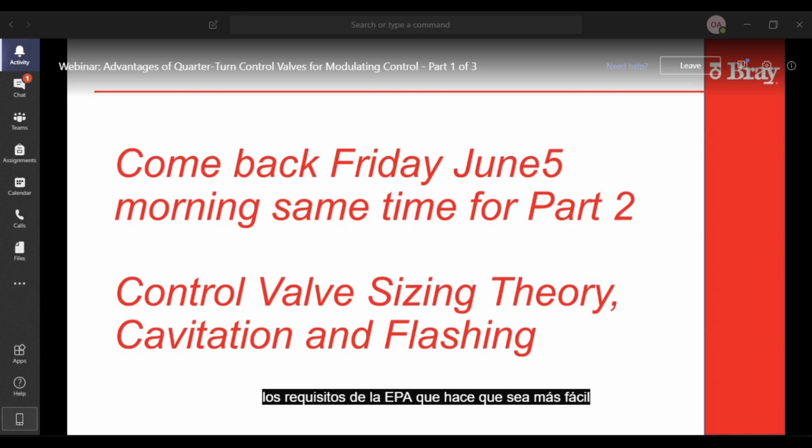It makes it easier to pass the API 641 test, but at the same time, ensures to the customer that both the packing has been classified and the valve type with the packing. So some manufacturers may charge more for that style of packing, but a lot of them, like ours, we standardize on it, so it makes it easy to stock one product. And that's probably what most manufacturers will do, so then it doesn't create any more cost as it becomes part of the standard.